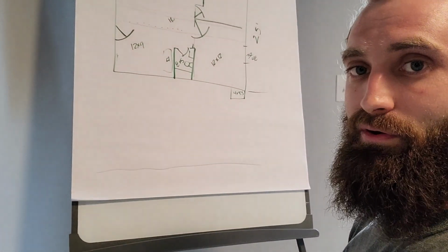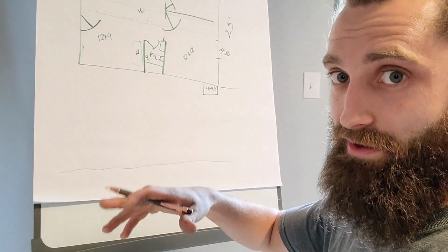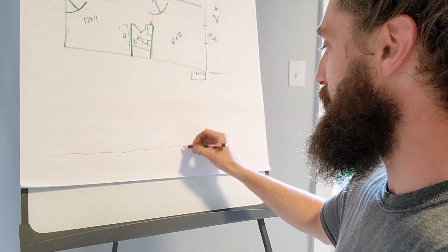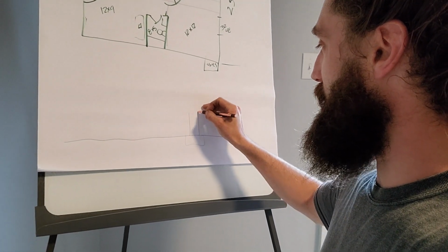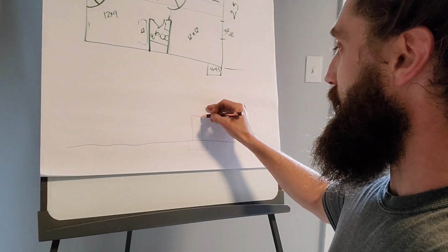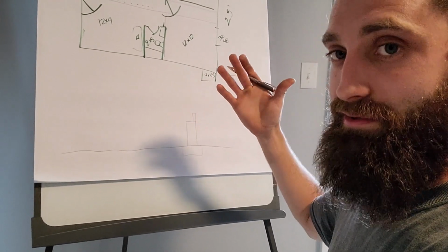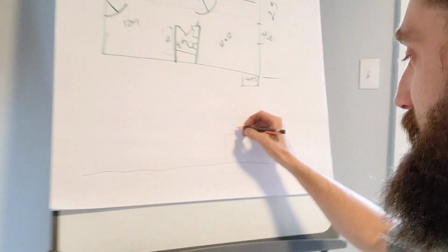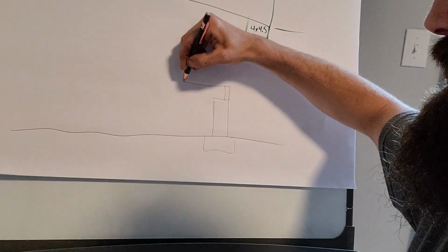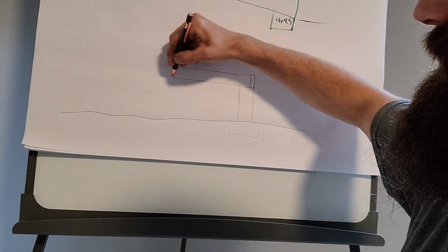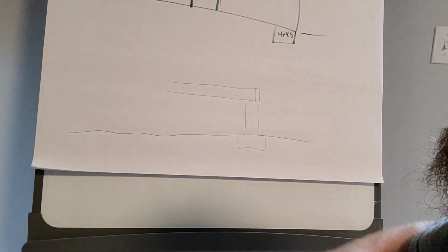Oh, I almost forgot. Yeah, so whenever we're looking at, I'm going to back up here, the crawl space itself. Now, this particular crawl space, we just think back to how the place is built. Okay, so we've got a footer, we've got our grade in the crawl space, we've got our foundation wall, and then we've got our sill that runs around, or our rim beam that runs around the whole perimeter of the building. We've got our joists that run across, and then we've got the fluffy stuff in between. So that's your traditional way of building a floor.